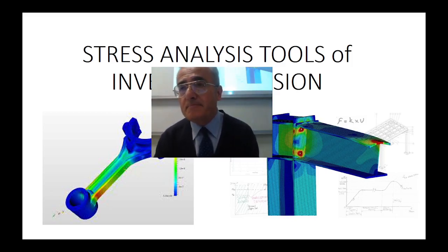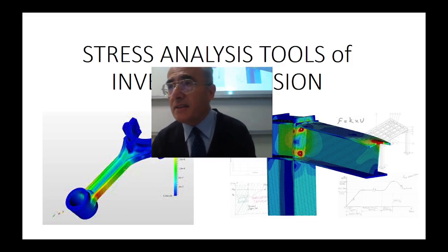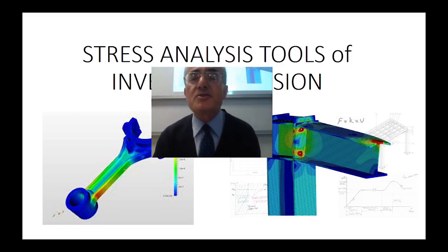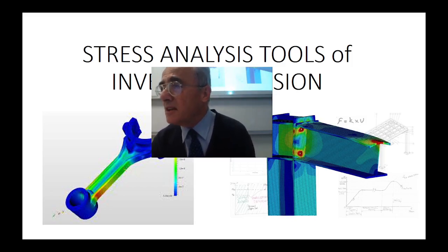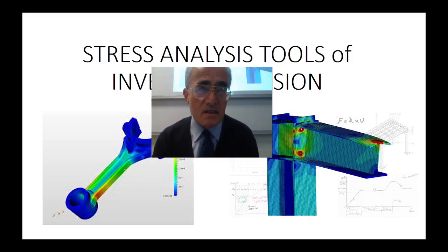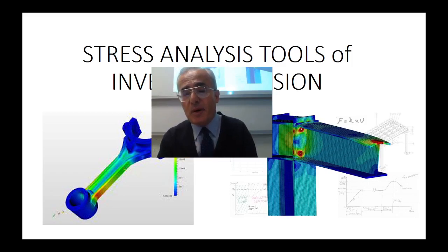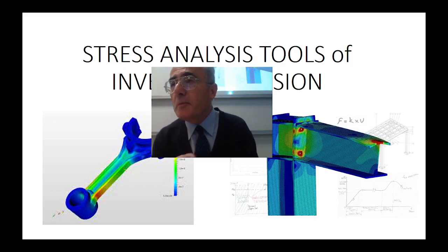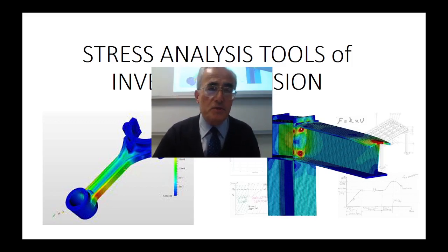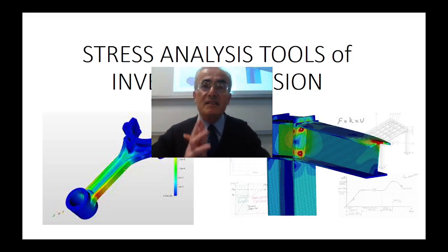If the geometry of the body is monotonously the same from here to there, its size not changing, its shape not changing, then use greater size elements, a coarse mesh. But if at a part of the body there is an abrupt geometrical change, two surfaces that would form a sharp edge if there were no flattening over there, then it's very critical.